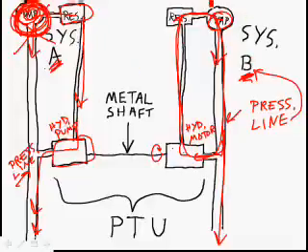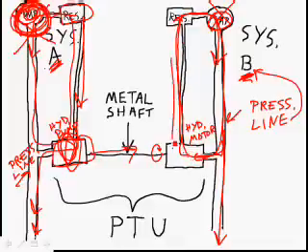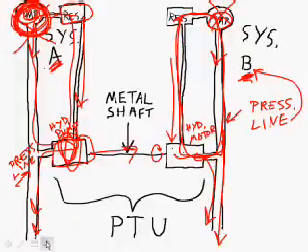So if system B pump failed, you could actually take fluid from system A, run this hydraulic pump. Of course, it would go back to its own reservoir, and power, only power, no fluid, would go from one system to the other. It would spin this hydraulic motor, and it would be pulling fluid from its hydraulic reservoir and pumping it to the system. So there's no transfer of hydraulic fluid. I've not seen an airplane where you could pump fluid from one system to the other, but you can take power off of one system and put it into another.